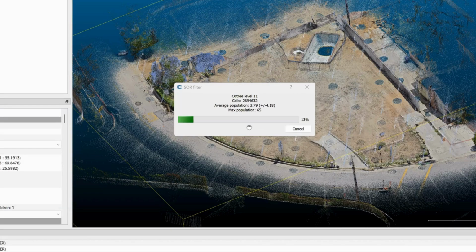What kind of tolerances have you been averaging across your projects when you do these as-builts or existing conditions? Within maybe an eighth of an inch? It's pretty accurate. The way to test that is to take the longest measurement you possibly can and then test it out in your scan afterwards. Take a measurement of more than 30, 40 feet somewhere and see how close it is. It's almost near perfect in that sense.